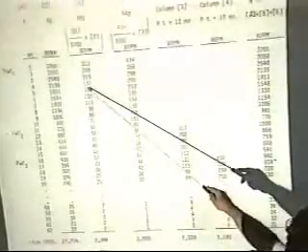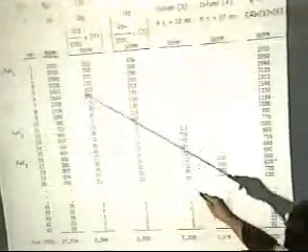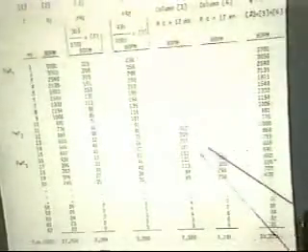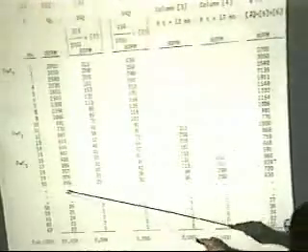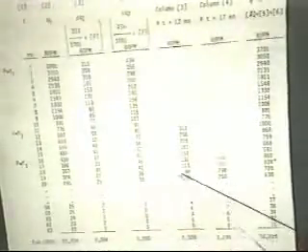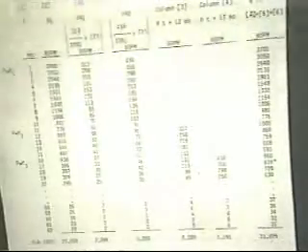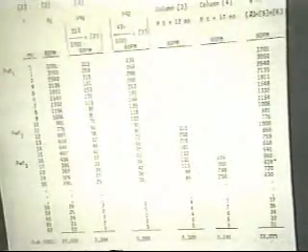But I've got to displace this rate to the time that it occurred. So I take this column, I move it over to here. I take this column at the time the back pressure was changed here. Then I go across and I add this rate plus this rate, which gives me the total rate as a result of back pressure changes, and the use of the concept of superposition.